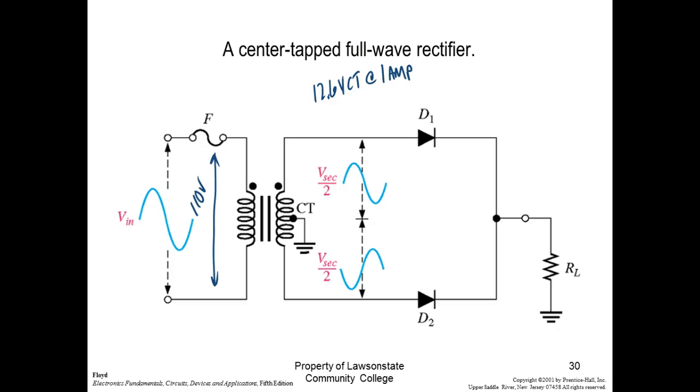So we should understand our output, our calculated, is going to be a little lower than our true output. And why is that? Well, we're getting about 120 volts out of our receptacles, right? And we're not loading that transformer to 1 amp. So where y'all going to start? Okay, voltage peak, good. So voltage peak, we'll do secondary, would be equal to 12.6 divided by 0.707.